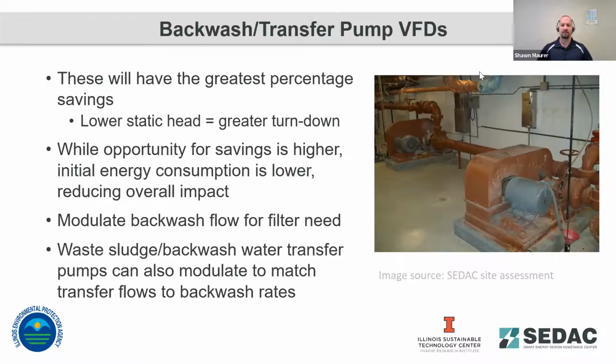And one other thing to note, system pressure is a function of demand from end users, plus the requirements from National Fire Underwriters and also the Department of Public Health. You have to maintain a certain pressure level to make sure you don't have water coming back into your system and contaminating your clean water in your distribution network. So there's a lot of interaction here between different regulatory groups.